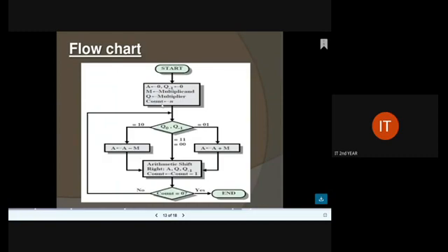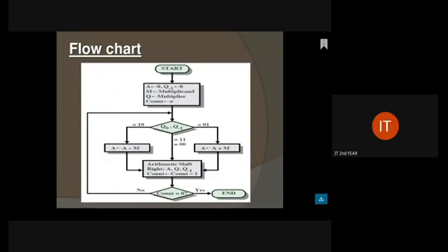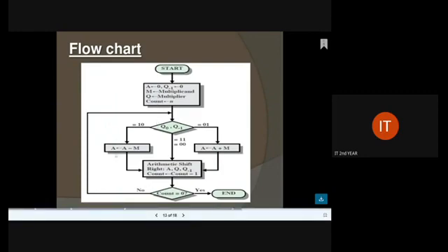Next one is count. It acts as a counter for generating each and every iteration. Next we have to look into the q naught value and q minus 1. When dealing with q naught and q minus 1, if the value is 1 0, then we assign a tends to a minus multiplicand. If the value is 0 1, then a tends to a plus multiplicand, that is, accumulator plus multiplicand.